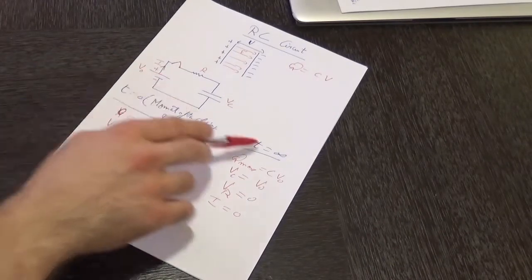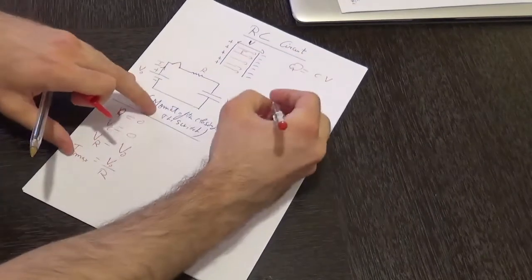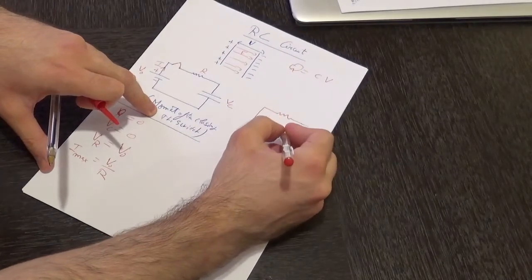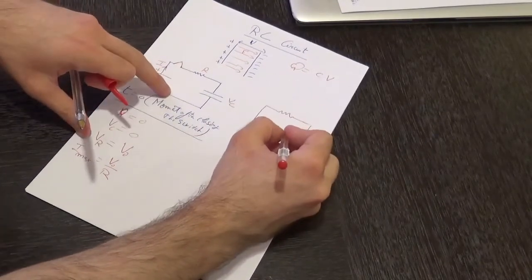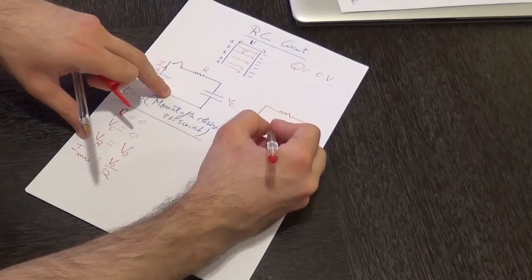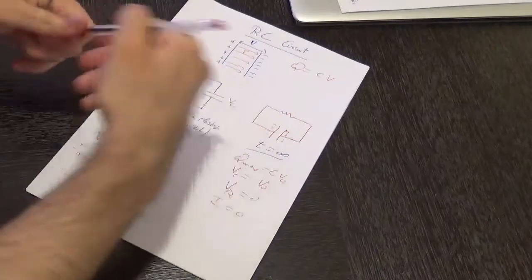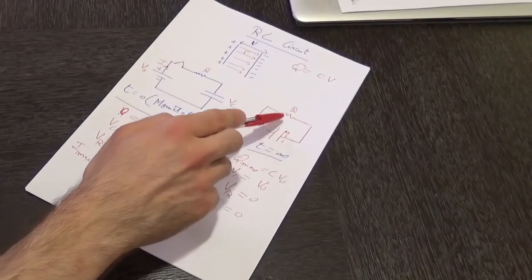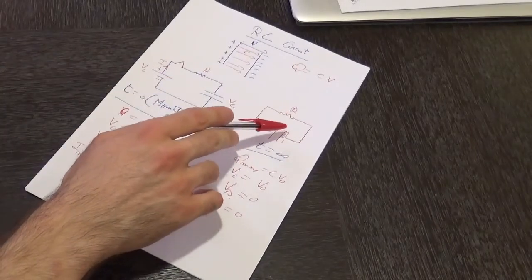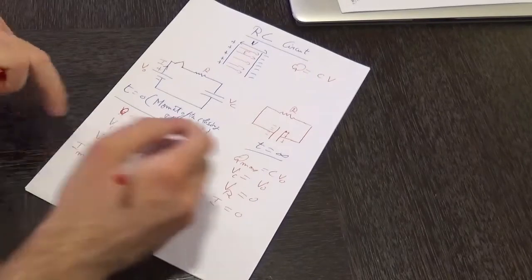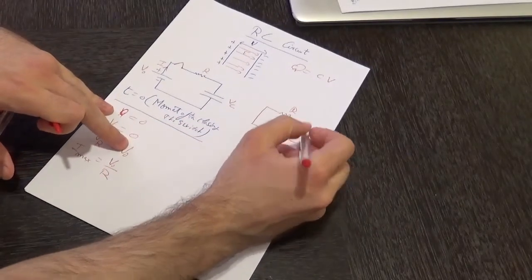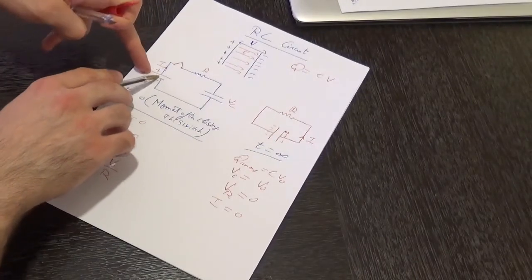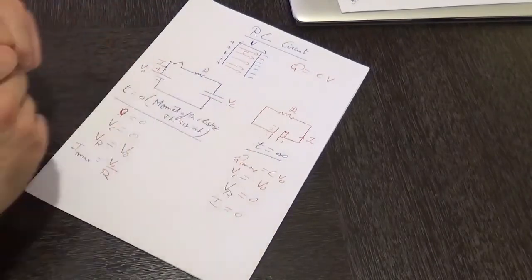Now let's consider that after t equal to infinity, we removed the battery and we kept the resistor only connected to that capacitor. So we know that the capacitor can behave like a battery. So it is fully charged. Over here we have the positive plate, over here we have the negative plate, and over here we have the resistor R. In that case, when removing the battery and connecting the capacitor solely to that resistor, now the capacitor is going to discharge into that resistor, meaning that now we have an electrical current that is generated by that capacitor, and as we can see, it's in the opposite direction of the initial current that was generated by the battery, and the discharging process of the capacitor begins.